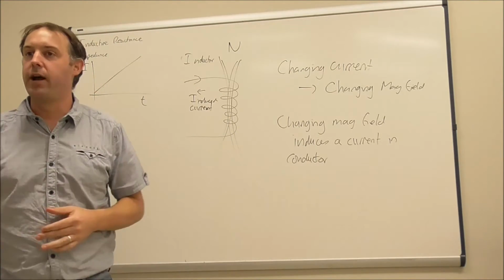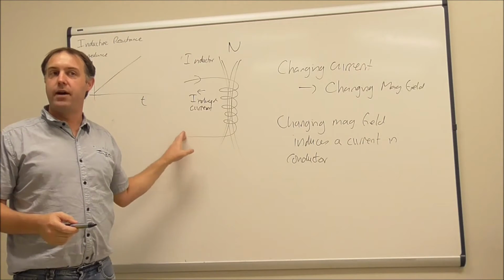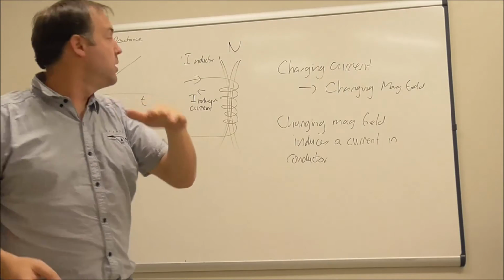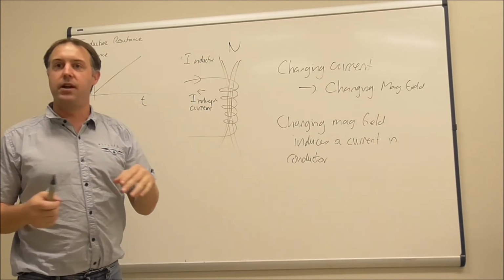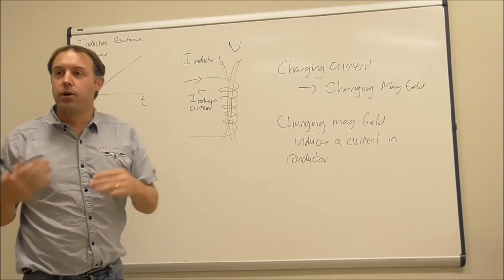Okay, so that's water hammering, and it's caused by, if I all of a sudden try and stop that water flowing, that water's moving, it's got momentum, it wants to keep moving, and if I try and stop it, it has to try and make all the pipes move with it. Okay. Similar sort of thing happens here.